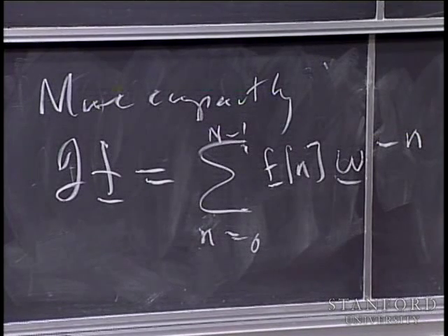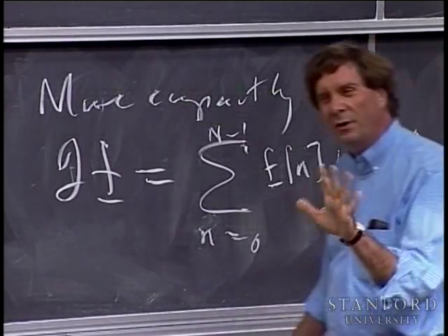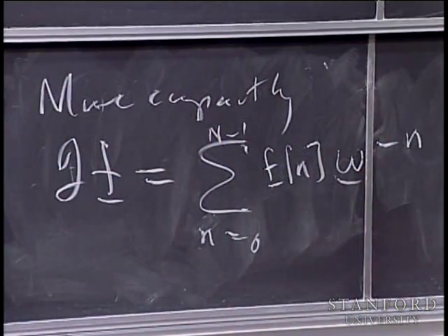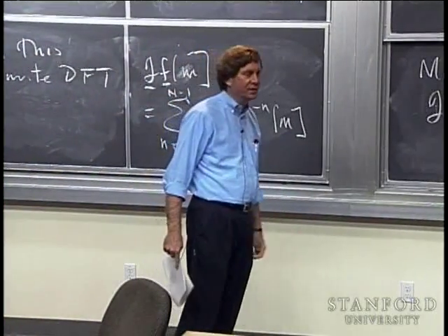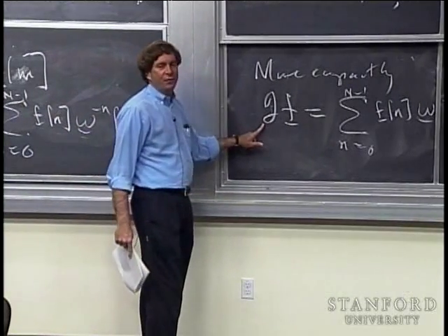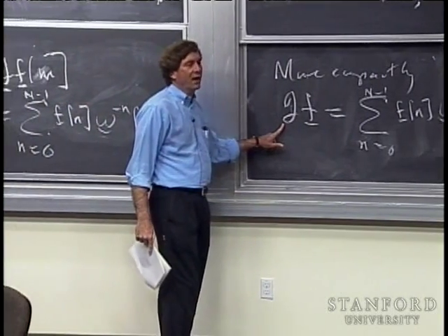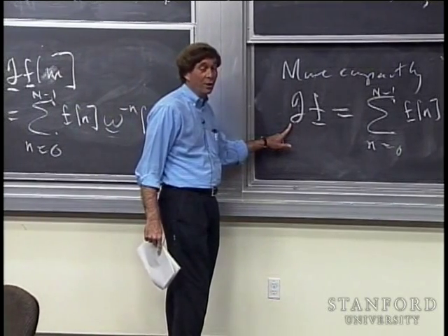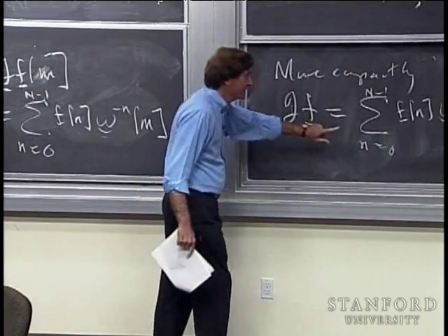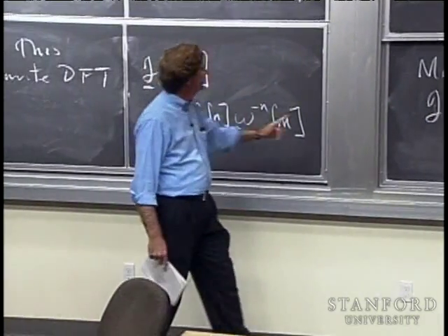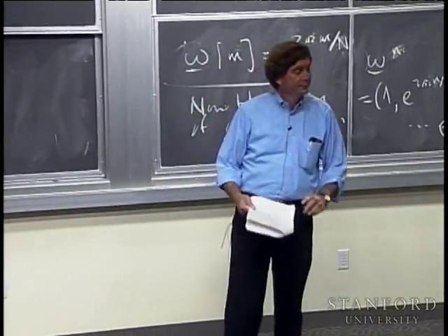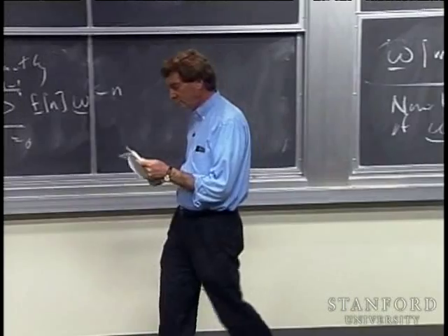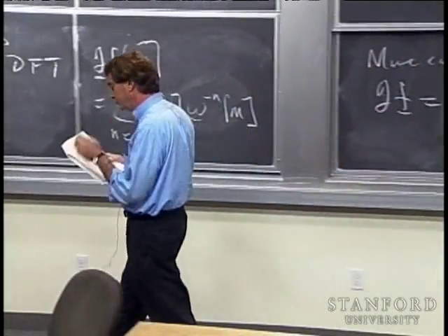Now, I find this a pretty convenient way of writing the DFT. It's always a question in this subject, whether in the continuous case or the discrete case, of when you write your variables and when you want to avoid writing your variables. So this is as far as you can go in writing the DFT without writing variables. In this case, the variable we're not writing is the mth index. Again, this expression is nothing but that expression evaluated at the index m, finding the mth component.